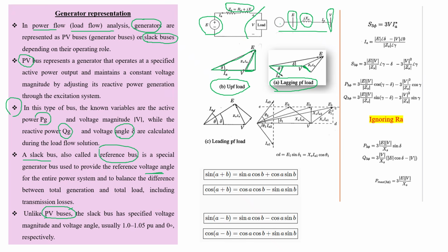So this is the voltage drop due to resistance. Again, the voltage drop due to reactance is perpendicular to the current. So we can have internal voltage, which has to be equal to the terminal voltage plus this drop. And again, we can calculate the magnitude of the internal drop when the generator is operating at a lagging power factor,